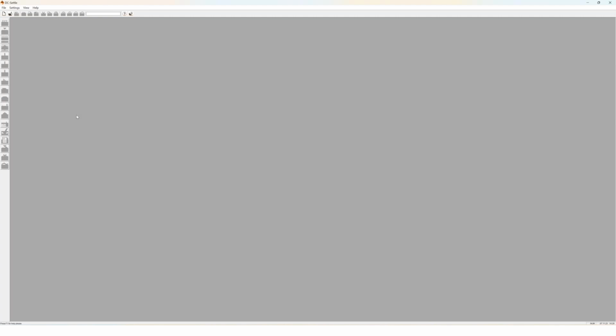EasySettle is a program where you can determine settlements for multiple load areas, and you can also determine the interactions for neighboring foundations if you want to. For example, when you want to build a new building next to an existing building without foundations, you can calculate the interaction from the new load, and you can see the settlements below the old foundations. I will show this later.